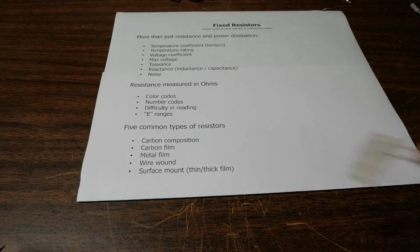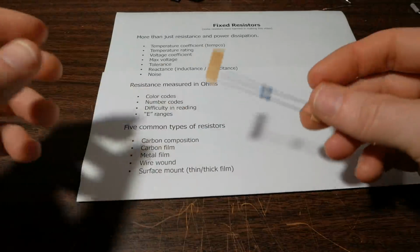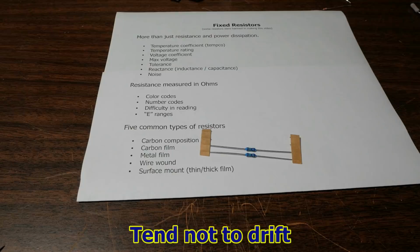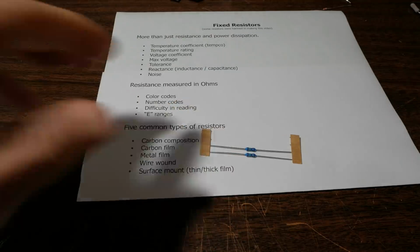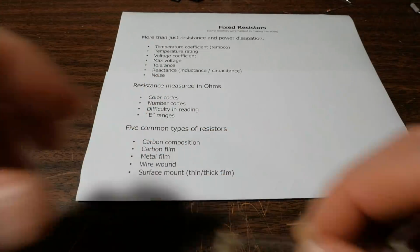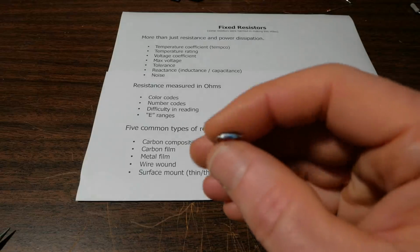Metal film resistors are superior to carbon film in about every way. They're not as noisy. They can handle surges a little better. They can be higher precision. But with that spiraling, you might have an issue with RF, though these usually work at very high frequencies.